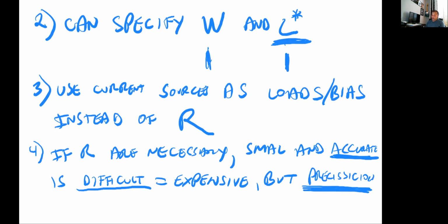So since I can be precise, if, instead of relying on absolute values, I rely on ratios, then the inaccuracy is going to cancel each other because I'm going to be always wrong in a very well controlled manner by some amount, but that delta, that error, if I rely on ratios, is going to cancel. And since the precision is well controlled, then I can get good accuracy from a ratio perspective.